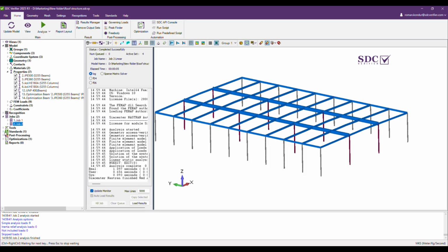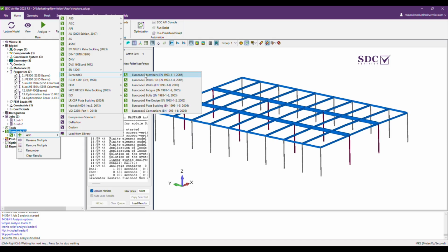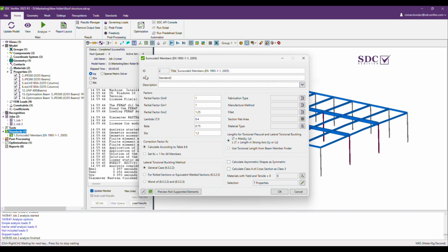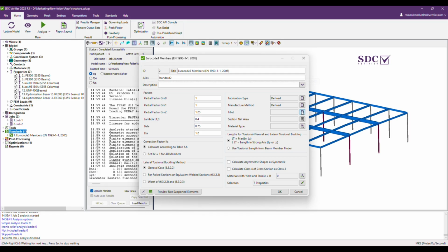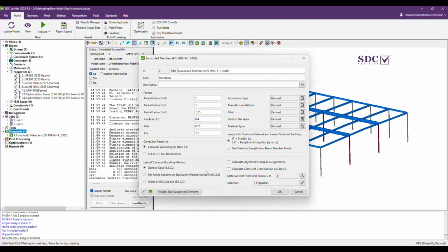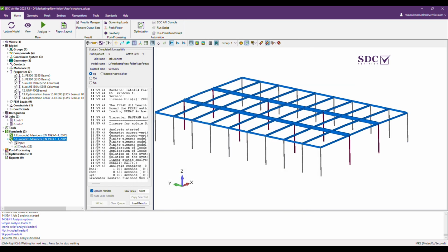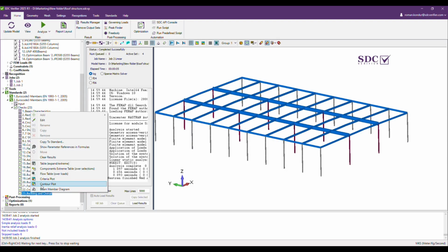And the model is calculated, and then we need to implement one more standard. So let's execute the same approach, Eurocode 3 standard, just to have the stored results of the previous results and the current results. So we will select previously rolled sections for all, finished, fill at 0, area, materials predefined. So that's it probably. Press OK.